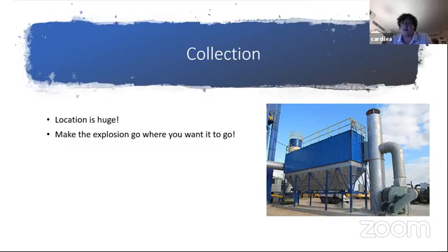Yeah, actually moisture in the air does have something to do with it. Not to the point where it's something you could really engineer differently. For example, if I'm in Arizona versus Virginia, obviously Arizona is way more dry than Virginia, but the moisture difference in the air is not enough for us to make a difference in the engineering. So we're still going to recommend the exact same things, but yes, moisture in the air does make a difference for a dust explosion. A more moist environment makes it less likely for there to be an explosion.